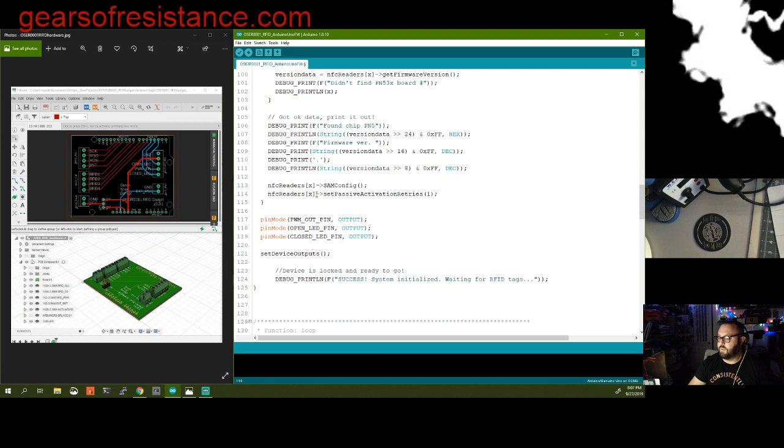Basically the next thing is sending it the configuration per the Adafruit PN532 library, and then next we're setting it so you get one retry, listen once, and then exit out and go to the next reader. If you didn't set this, the first reader would sit there and wait forever until it saw an RFID tag go past that reader. So by setting the value to 1, it lets us walk through each reader one at a time. If you notice that it only looks at one reader, check this. This is what you may have missed if you're running your own code from scratch.